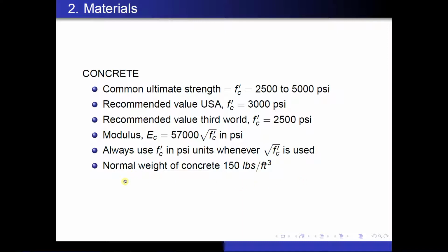Lastly, as you know, when you are designing a structure, you do have to calculate the weight of the structure itself, and that, of course, contributes to the dead loads. For normal weight concrete, it is common to use 150 pounds per cubic foot. Now, that is what people use all the time. That includes the concrete, and it already includes the reinforcement that is included in the concrete also.